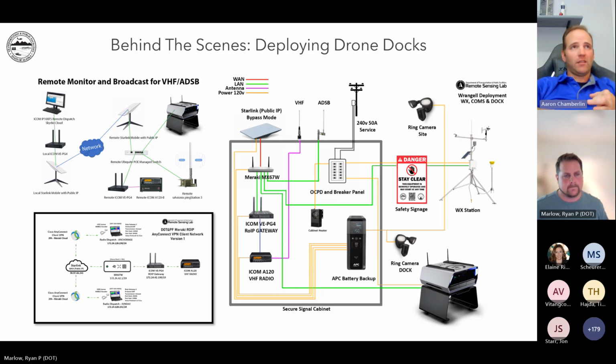And then again, inspecting the props. On the Skydio system, there have been issues with props pinching on the X2 system as that door closes. Those have really been the only 2 issues we've had. Some systems have demonstrated more reliability than others. One of our systems has 250 flights and has literally not had a single issue. I swapped out the props because we were getting 25 hours on them and it was time to switch, but they showed no signs of visible wear.